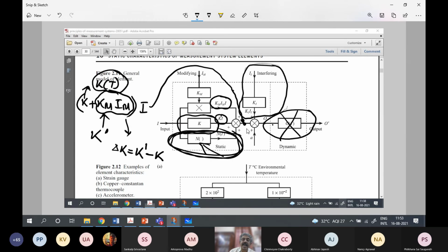If you work on a longer range scale, say a 500 degree centigrade scale, it will give you a reading for 50 degree centigrade. It will also give you a reading for 600 degree centigrade. Then obviously such a description will not be applicable. If you apply it, you will have errors. So then you may give a table of a thermocouple with some equation saying that it is actually a polynomial. Then you can include the nonlinearity description within the description of the instrument.